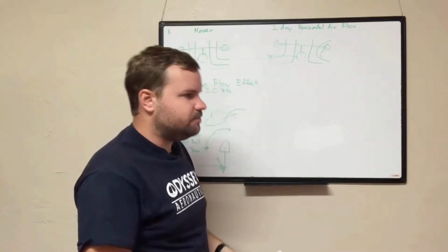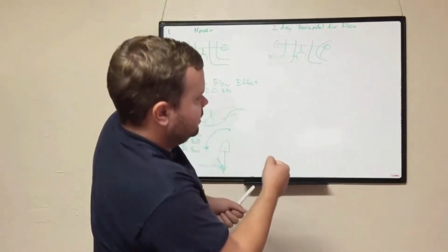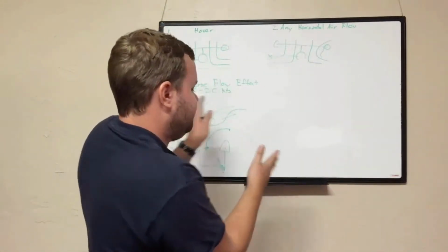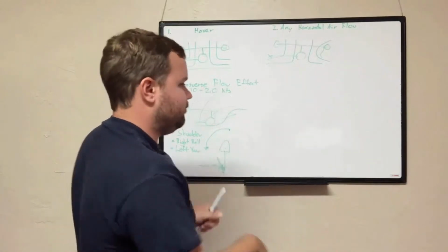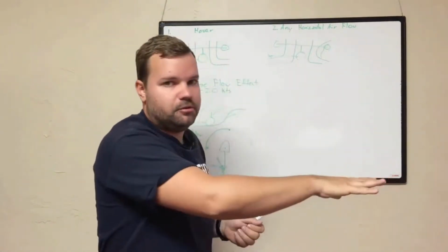The nose will kind of dip up and they weren't anticipating, so they'll nose over, then it'll roll to the right, so they'll push left, and then the tail rotor will swing you to the left, so then you're too late pushing right pedal, and you get this kind of fishtailing weird thing until you've blown through it.